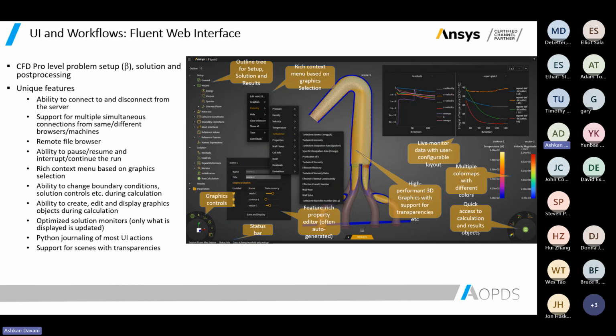So using Fluent Web Interface, you can open the setup from your browser anywhere. You can connect or disconnect to the server. You can set up the case. You can pause, resume, interrupt the run. You can save the data. The residuals have been optimized for this view. You can actually journal using Python.